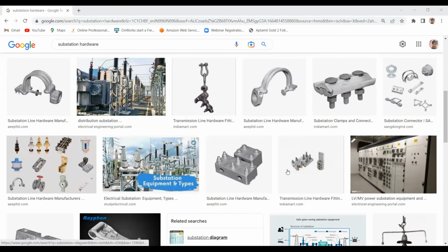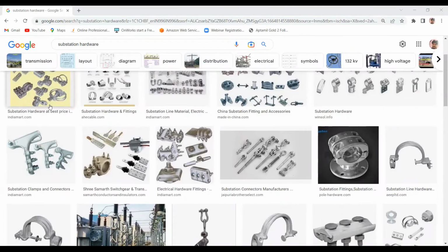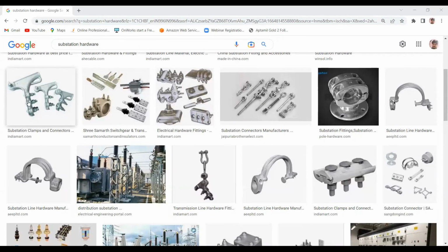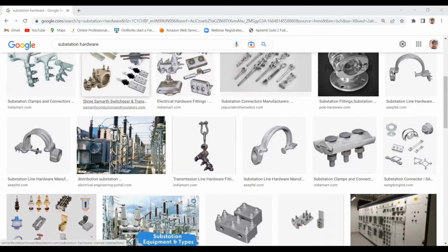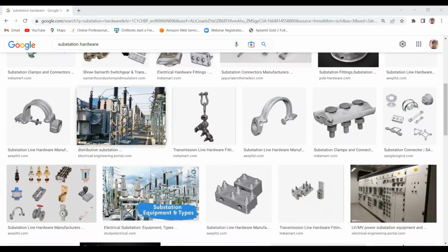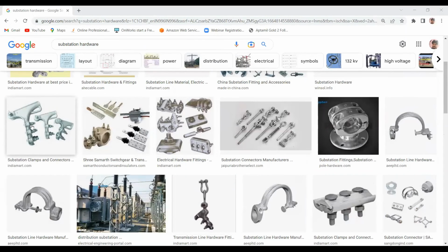Yes, sir. So here you can see, team, these are the tension hardware, what I said is used to string these conductors. These are the tension hardwares. And this is the clamp we are connecting to that boom. And from here, the conductor will go through this. It is tightly packed with these bolts. We will loosen these bolts, so this U shape will come up.